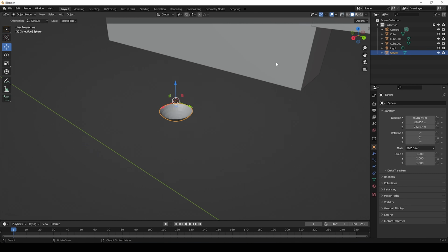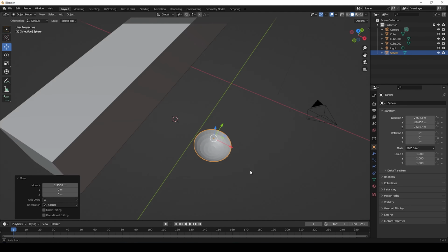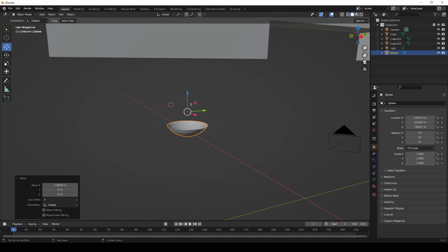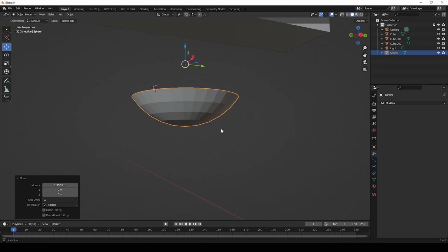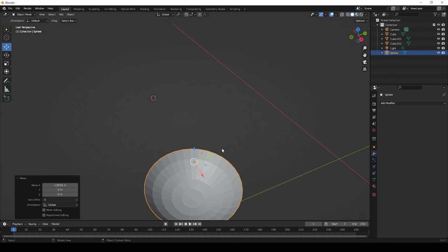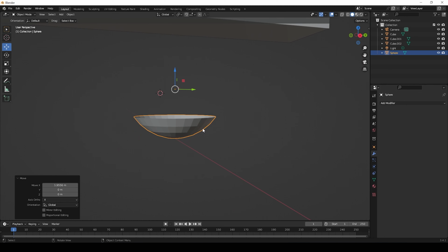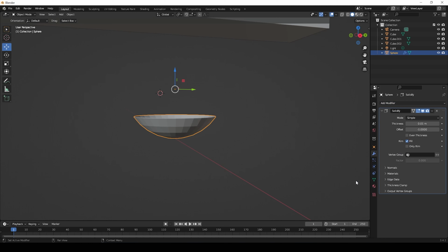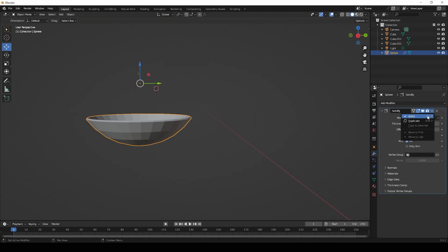All right, so we turn off X-ray mode, go back into our object edit mode, and now we've got our first parabola antenna built out. Eventually I'm going to be 3D printing this model, so I'm going to add some thickness to the shape that was built by Blender. Most of Blender's shapes are impossibly thin, so really difficult for a 3D printer to add those in a layer by layer sense. So what we're going to do is click on the shape, click this purple wrench icon, add a modifier, and do a solidify. Maybe take this up to something like a 0.3. Okay, it's looking nice and girthy now. I think that's probably good. We'll go ahead and click apply.